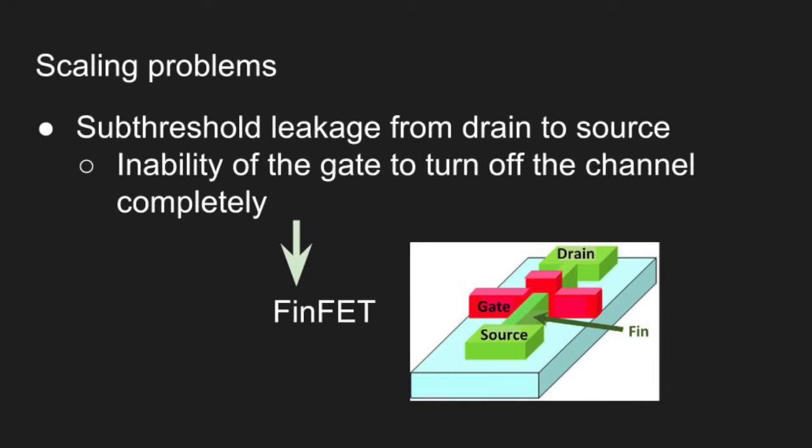As we reduce the size of transistors, the gate may start losing control over the channel, and there may be some current flowing while the transistor is in the off state. As we will later see, to overcome this, FinFET transistors were designed.